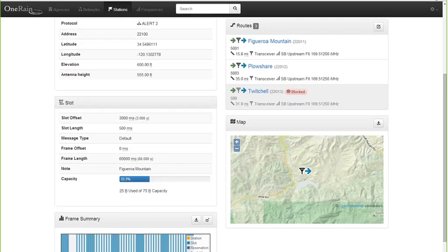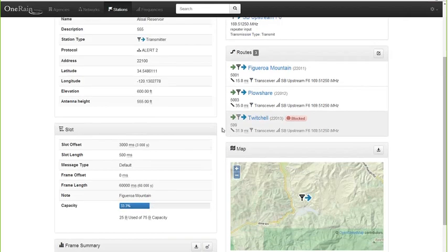So therefore, we're good. We're only using up about a third of the slot capacity, but this 25 bytes will fluctuate. We might end up sending 2 messages during this transmission, which would be more than okay. We have plenty of space, plenty of unused capacity at this slot level.